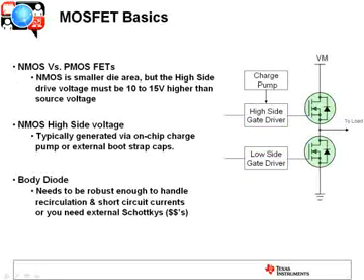Now when looking at the FETs themselves, one of the first distinctions you'll see is, are they NMOS or PMOS FETs? The advantage of the NMOS, at least from a die area, is that it's much smaller. This is especially true at the higher voltages. At some of the lower voltage nodes, 5 volts and below, they can actually become fairly comparable in terms of die area and cost. But at the higher voltages, for sure, the NMOS is much smaller, which equates to lower